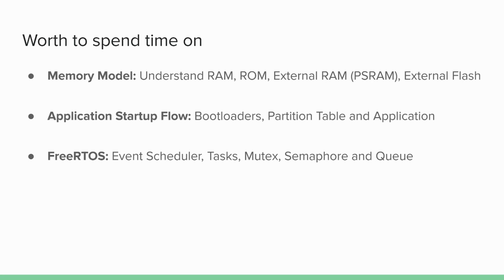We are using FreeRTOS on ESP32 because usually ESP32 runs complex applications. Even if those applications seem not complex, when you are running Bluetooth or Wi-Fi, those are already complex tasks for a processor or controller. So FreeRTOS helps us to manage that. If you have other peripherals such as an LCD or graphical display, FreeRTOS helps us to manage complex projects.